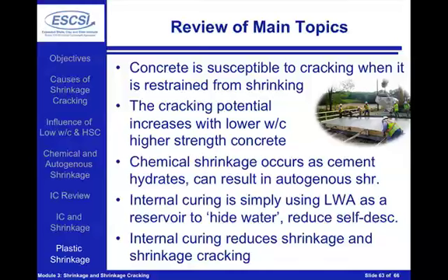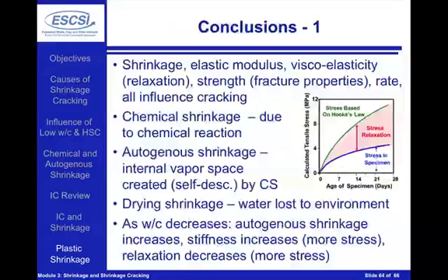Internal curing will reduce the self-desiccation by filling in the vapor-filled spaces that form. The lightweight aggregate will hold the water. That water will leave the lightweight aggregate, fill in the vapor-filled spaces, reducing self-desiccation and in turn reducing autogenous shrinkage. Therefore, internal curing reduces shrinkage and shrinkage cracking.